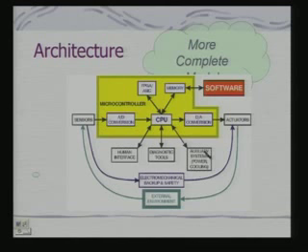And you have the auxiliary systems which are to be dealt with power, because if there is power dissipation, then cooling becomes an essential component. So, how to design the cooling circuit, how to take care of extra heat dissipation, and all these mechanical aspects of this design become important. Obviously, the casing, the whole system should be properly packaged, and the packaging should be as per the requirements of the external environment in which the embedded system is expected to be placed. So, this packaging becomes a very, very important issue.